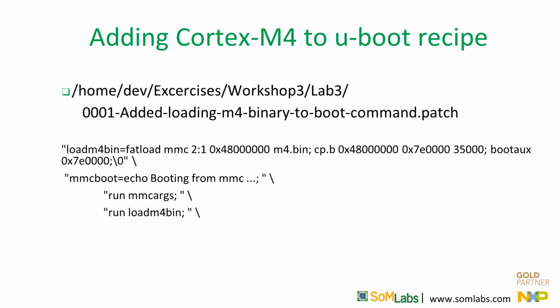To run the M4 application in the previous example, we had to enter a series of commands in the U-Boot console. This process is automated by the patch added loading M4 binary to boot command patch. It creates the load_m4_bin environment variable in the U-Boot environment, which contains all of these commands, identical to the ones entered manually in the previous example. They will be run while executing other commands contained in the mmcboot variable.